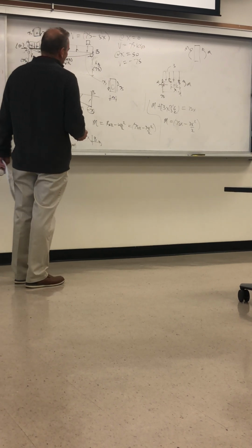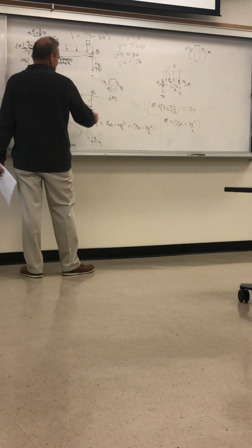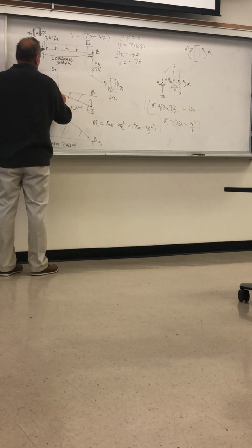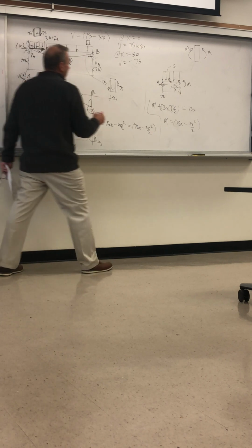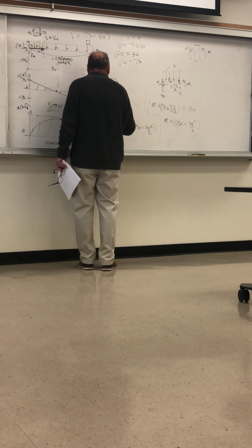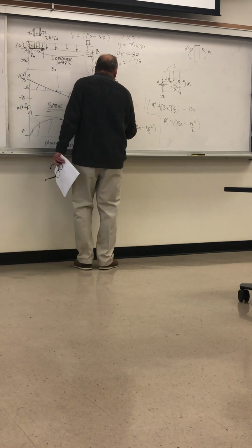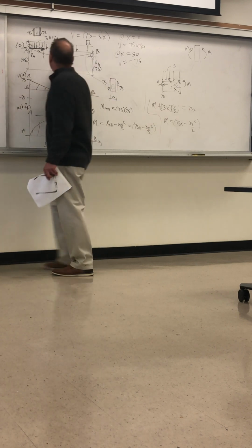And so we have this as a moment expression, the maximum moment. You can use this equation, or you can just determine it directly. It's going to be at this location here, this value. Moment max. We'll just calculate it directly. 75 times 25. So that's the moment in the middle.